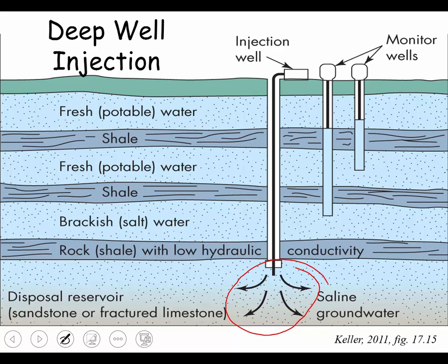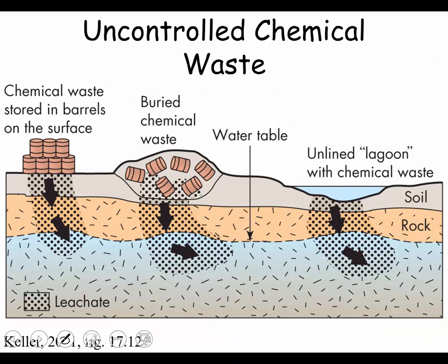Now, as you also know by now, this can result in earthquakes. We see that with fracking, large volumes of water that are being injected into deep reservoirs. If they're injected too fast, they can decrease the shear strength by increasing the pore pressures and therefore cause earthquakes. Okay.